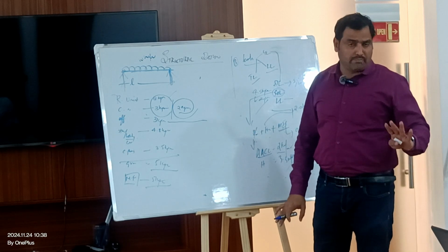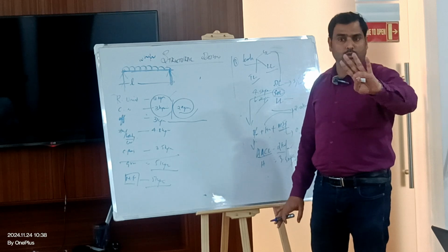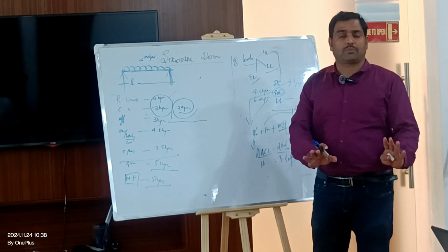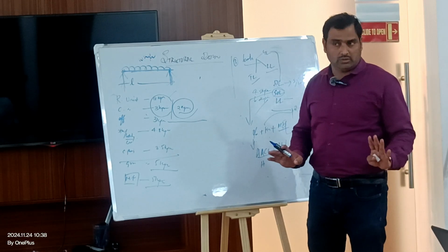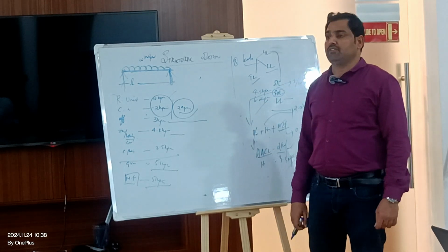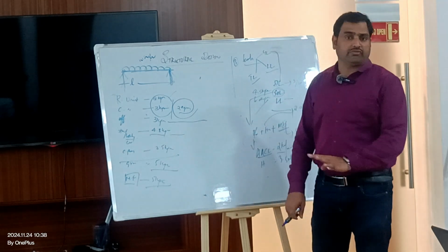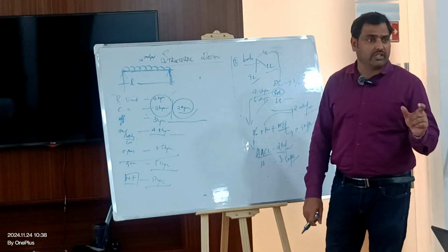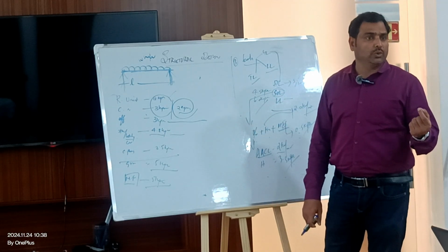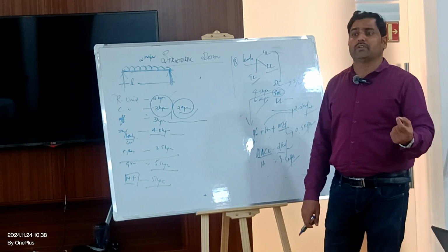It is not mandatory that you follow 3 for the entire building. Nobody is going to force you. The only thing is you need to substantiate with the architectural drawing. That's all. Going with the common areas, which are staircase, lobby, corridor, it is all 4.8. Why not 5? Why is it only 4.8? What is the difference between 5 and 4.8? Only 20 kg per square meter. The reason is that the code is giving a privilege.